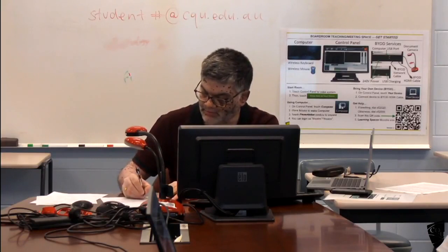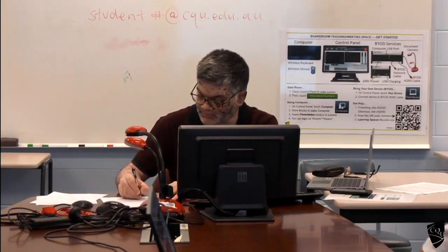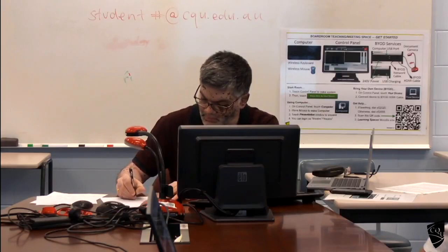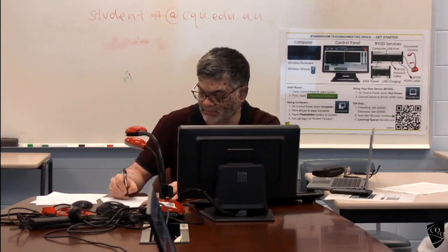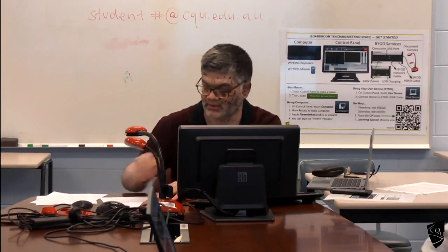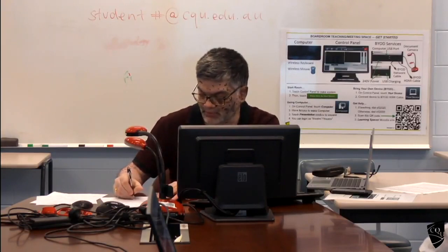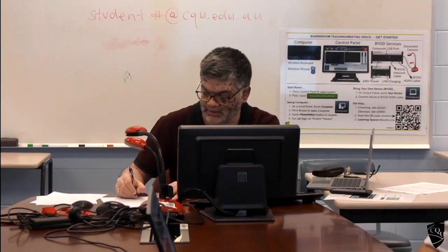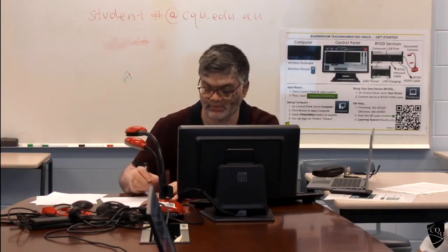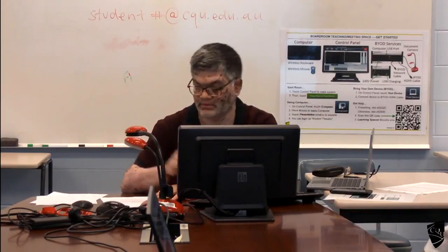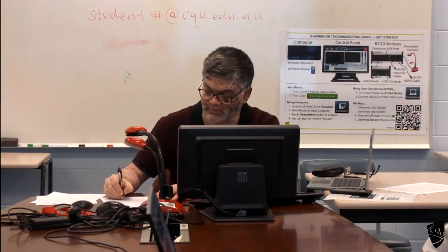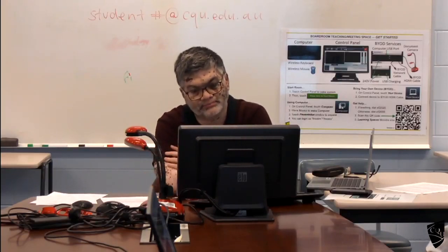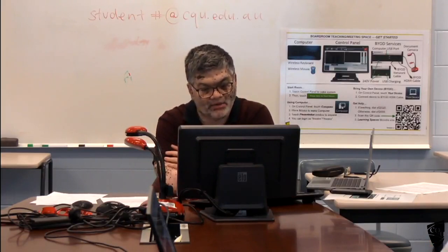So then you will provide the reinforcement on the top. For the 600 kilonewton meter, B is equal to LT upon 2. So you should be able to find out, the D is known. From that you should be able to find out small d, and you should be able to find out the area of steel. So that is how normally we work out the area of steel for the flat slab.